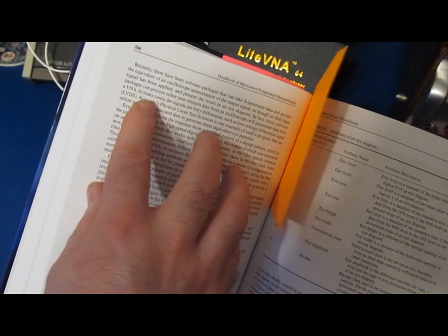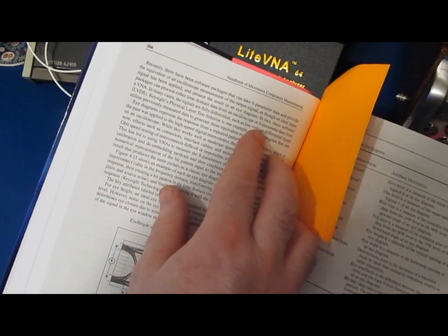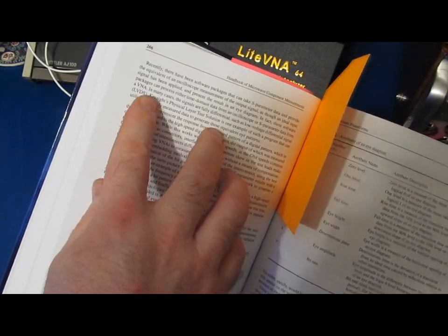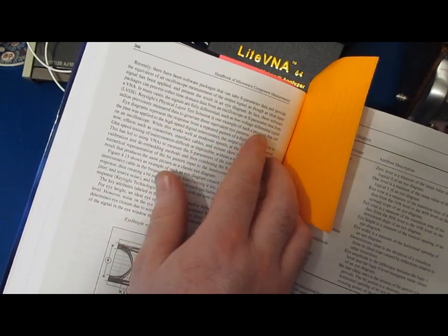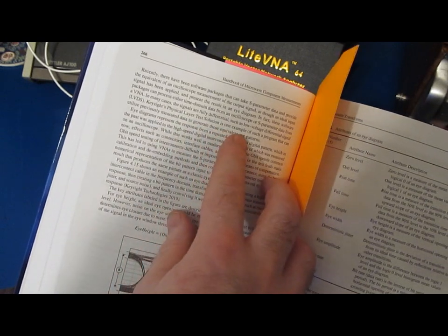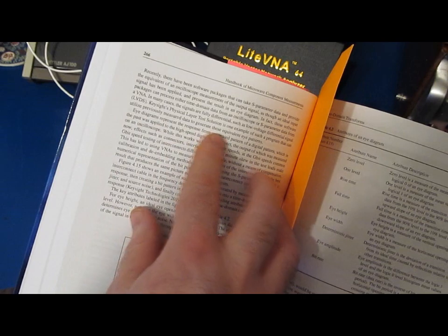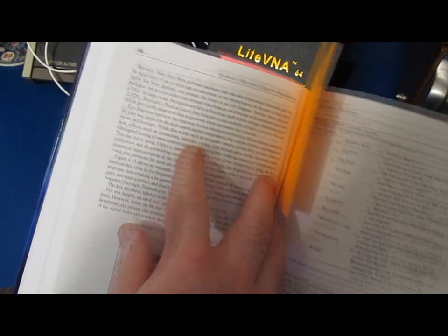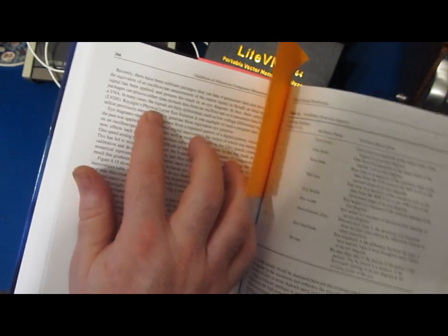In fact, these software packages can process either time domain data from an oscilloscope or S parameter data from a VNA. In many cases, the signals are fully differential, such as low voltage differential signaling. Keysight's physical layer test solution is one example of such a program that can utilize previously measured data to generate these equivalent eye patterns."